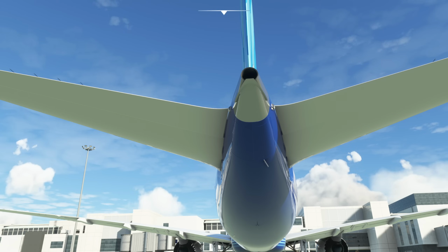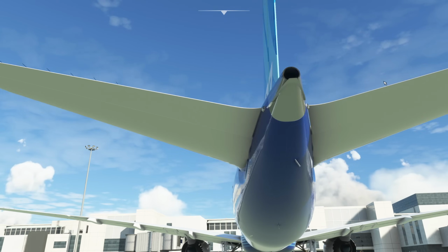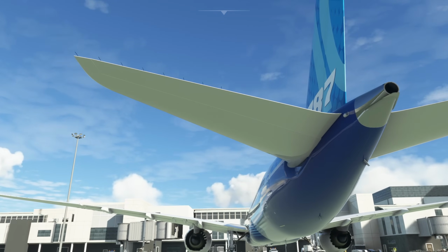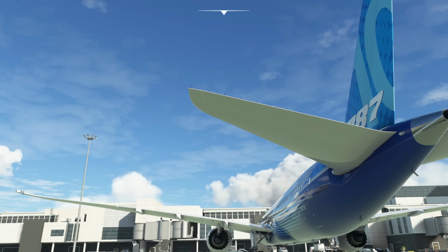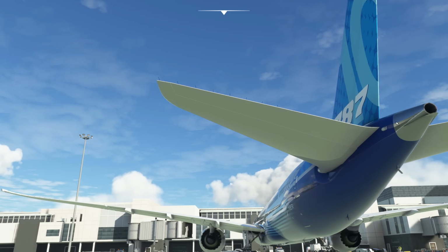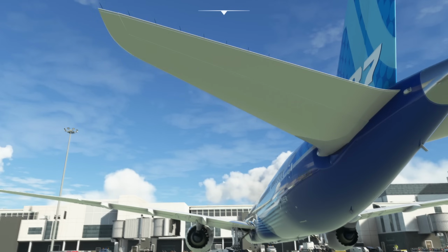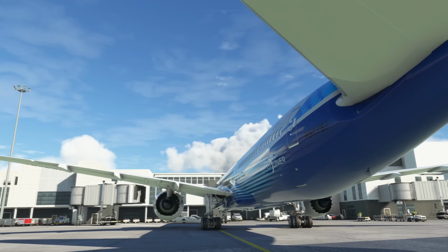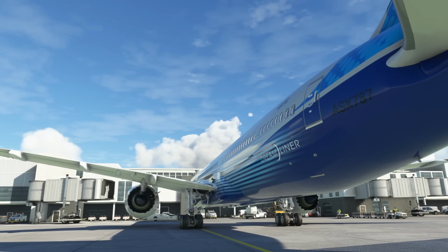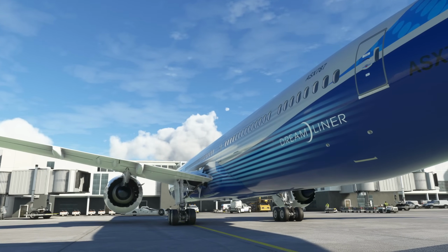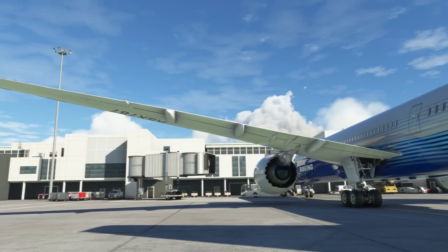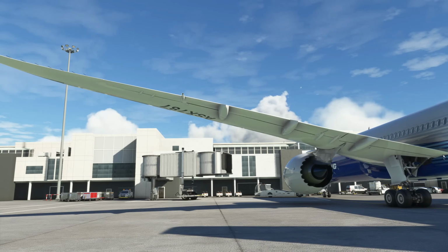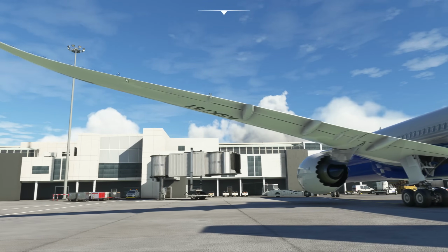These are the rear strobe lights, which you can see, left and right to the tail, quite an iconic part of the design. And the actual navigation rear light is put on the wingtips, quite common for Boeing. So these are the rear nav lights, these are the anti-collision strobe lights. As we move down the other side of the fuselage then, I won't take you all through it again, but you do a repeat of what we've just done, checking out all the different bits of the 787's fancy systems. Often these inboard ailerons will be drooped down, or any of the controls will droop down.